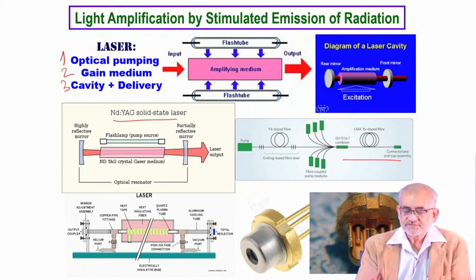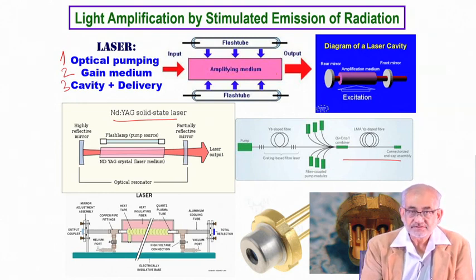Anyway, so these are various possibilities. Since I mentioned the fiber laser being one of the most widely used these days, that happens because actually it's very convenient. The active medium and the delivery medium are the same. So essentially long optical fibers, and some of them come with certain pumping devices, diodes, which will actually pump energy into them, and so all of them will create a bundle, and that's where they get combined.